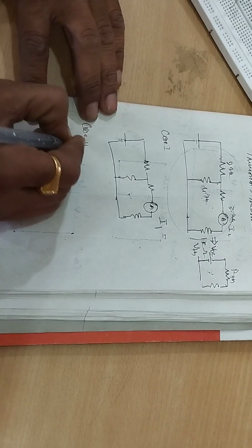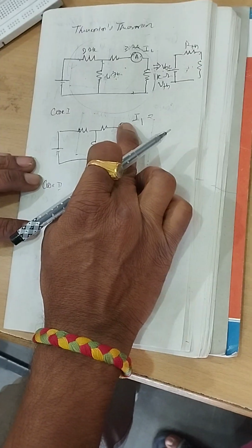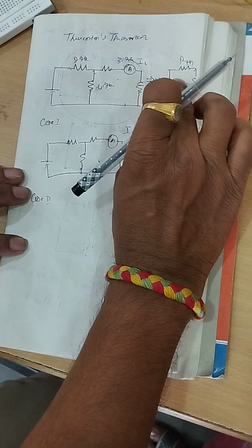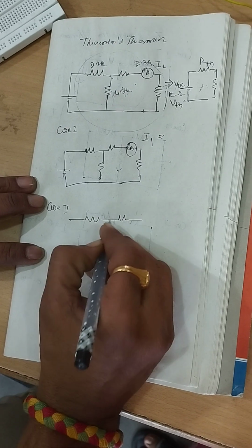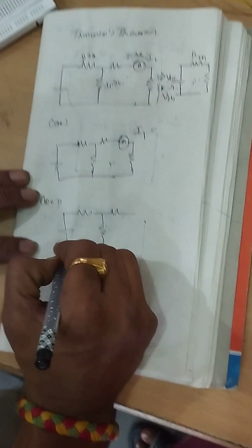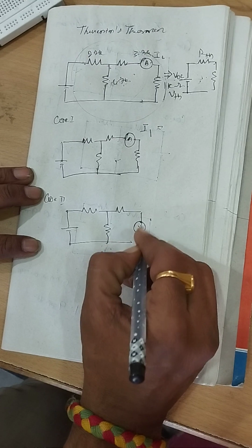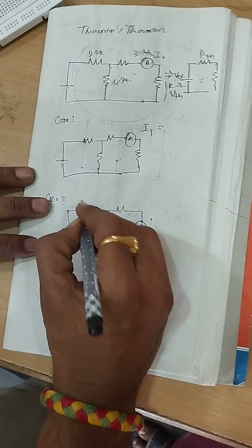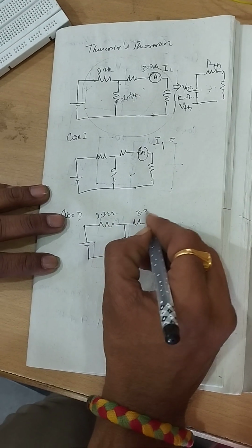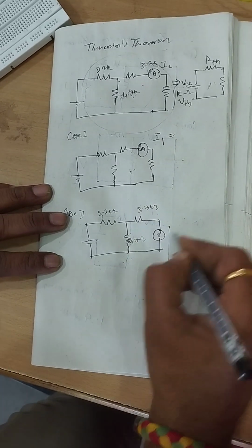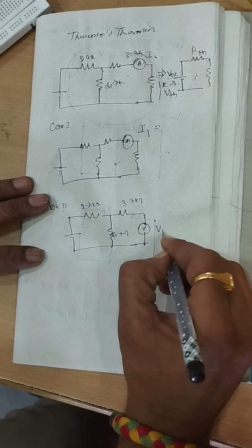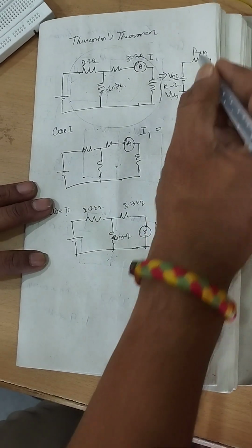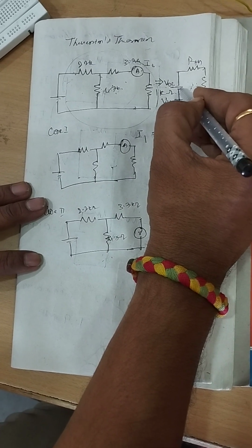Case 2. So we should know the voltage. This is a reference, a check to justify the theorem. Now let us come to the actual circuit. This is called open circuit voltage, which will be measured by removing the load resistor and keeping a voltmeter in replacement of the load resistor, with 2.2 kilo ohms, 3.3 kilo ohms, 4.7 kilo ohms, and connect a voltmeter across these two terminals and measure the V Thevenin's voltage, which is required to set the voltage in the equivalent circuit.